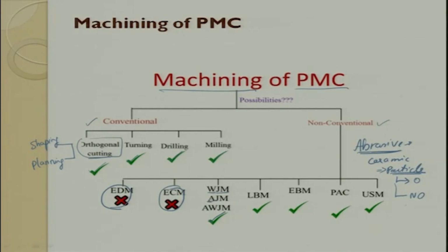There are two types of classification, one is oxide ceramics and non-oxide ceramics. So, here these are very small particles, from 1 micron to 10 microns you can have, and it is used. So, the abrasives are small particles. These particles are pressurized and they are mixed with a carrier gas, so that they get the pressurized air exiting the nozzle while cutting. And if you want to have a hybrid of air and water put together, those processes are called abrasive water jet machining process.